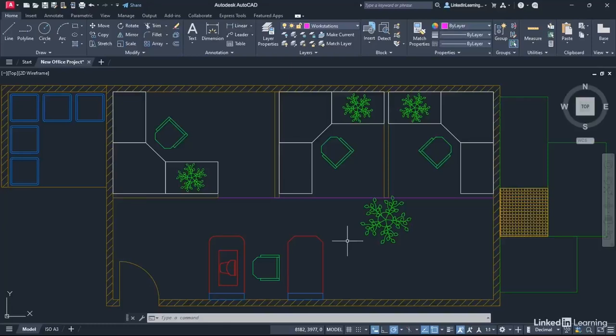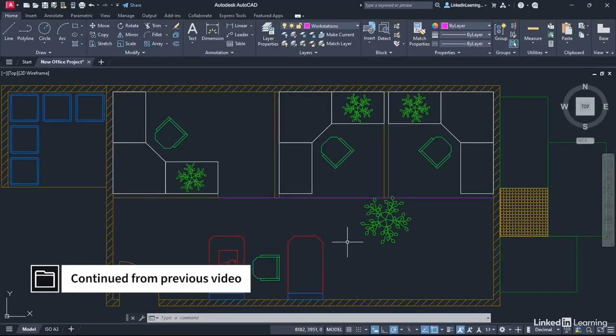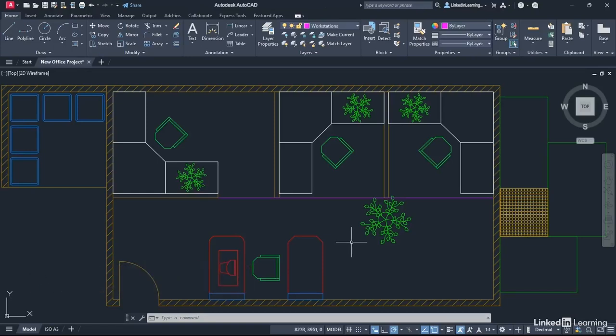We're staying in our new office project.dwg file. And in this particular video, we're going to take a look at creating a simple dynamic block. Now, we've mentioned regular blocks already, but with a dynamic block, you can apply movement parameters to the block. So you can potentially flip the block, move the block, and do it automatically with parametric actions.